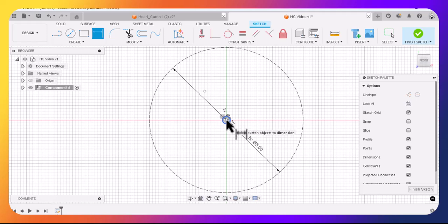I'm going to say that from here to the center there, going across, this is going to be my nominal diameter divided by 5. And then I have my nominal diameter divided by 8 for my height. Enter. And there is that point there.